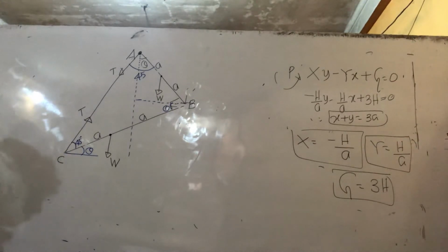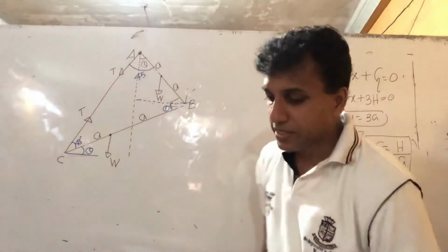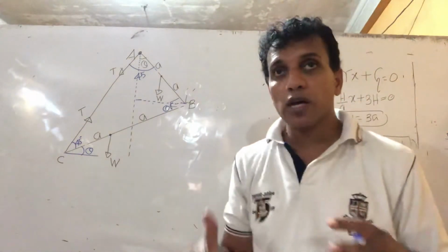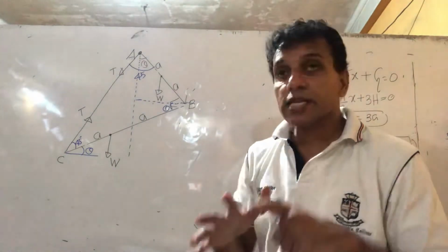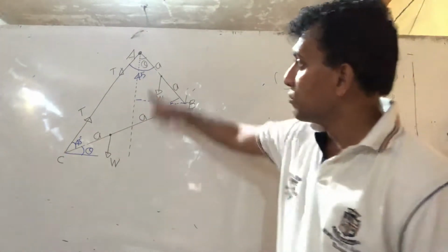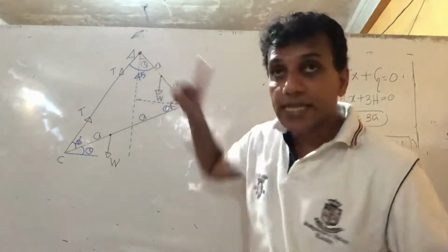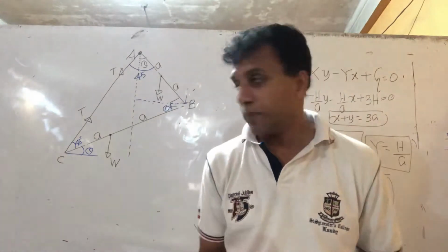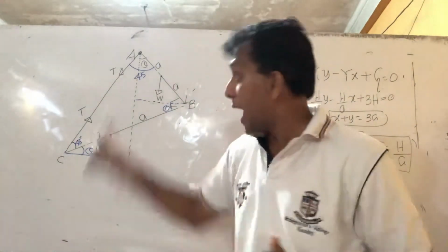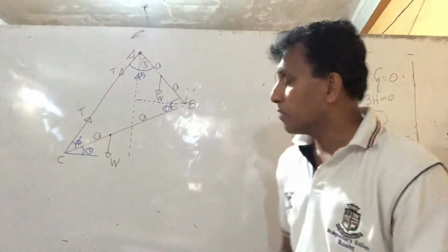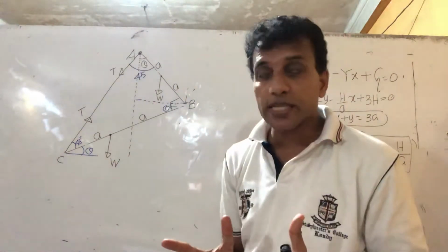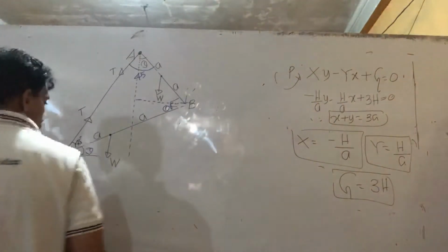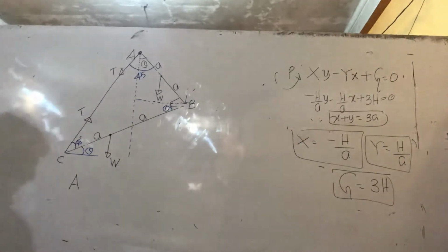Okay, right. So what is the idea to find the theta value? Think of any method. We want to eliminate the forces, so without a force we take an equation. Therefore take the complete system. For the system, if you take moments about A, what happens? T cancels. The joint reactions also cancel. Only weights are available, right? So on this side W, and some distance and angle come, and you can find the first part answer. You have to write this first: for the system, take moments about A. So we mark the A here.